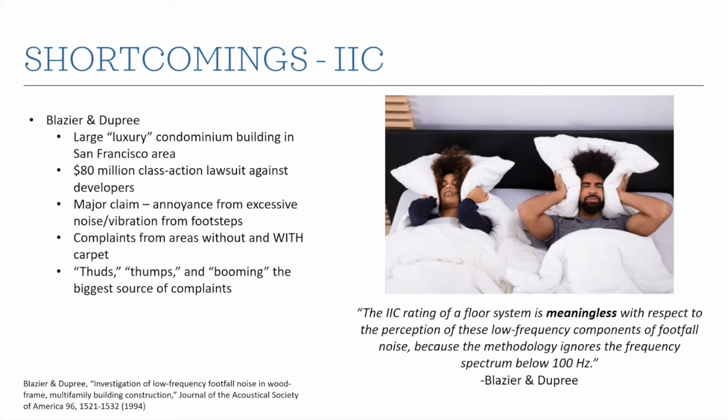And I think this is a very interesting quote from this paper. It says the IIC rating of a floor system is meaningless with respect to the perception of these low frequency components of footfall noise, the thumps and thuds and booms, because the methodology ignores the frequency spectrum below 100 hertz. I just showed you that graph, and it goes from 100 hertz to 3,150 hertz, but we can hear things well below 100 hertz, and those sounds are important.